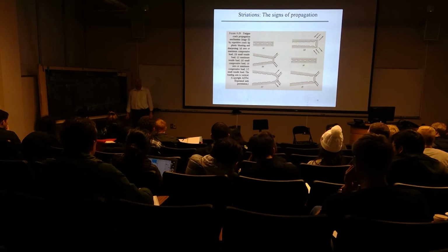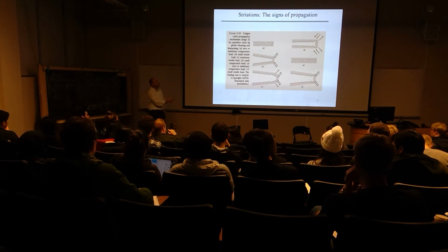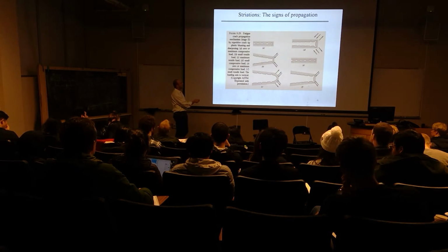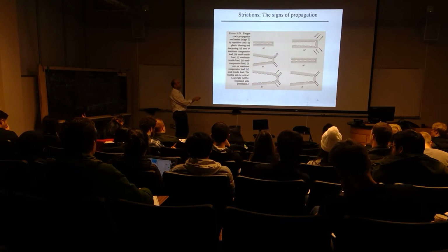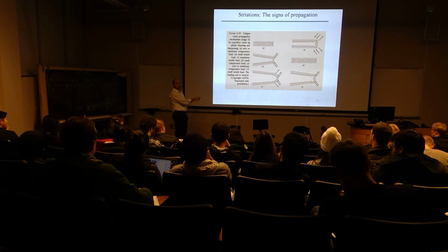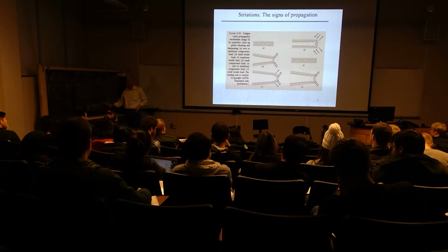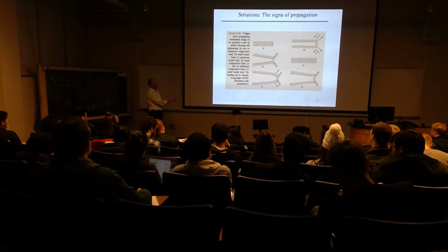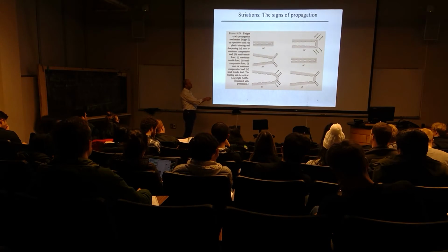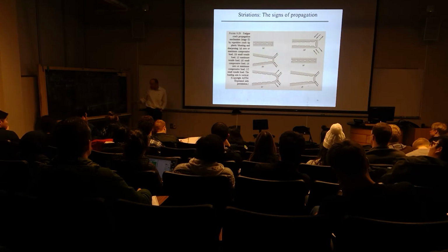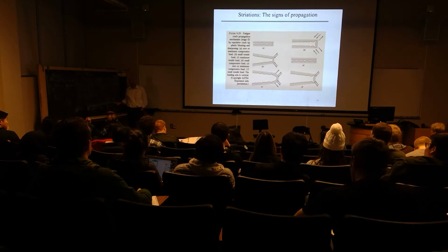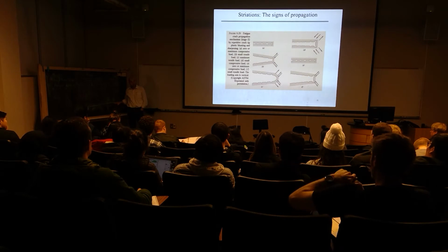But in reality, if that material has any ductility, then we'll see a pattern that's quite different. So envision that this is a crack starting from left, growing to the right, and it's reached a point where we're going to examine it. When this is close to stress-free, or it's subjected to a small amount of compression in the cycle, the faces of the crack are closed. But then when you apply a little bit of opening mode load, because of the intensification of the stress at the crack tip, the huge increase in the magnitude, there will be potential for plastic deformation to occur near that crack tip.